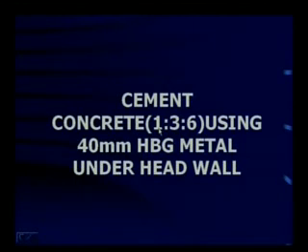Yes, 1 is the cement, 3 is the fine aggregate, 6 is the coarse aggregate, and we use 40 mm hard broken granite metal for the coarse aggregate. This is used for filling the excavation under the head wall. Rather, I can call it a base material for foundation.